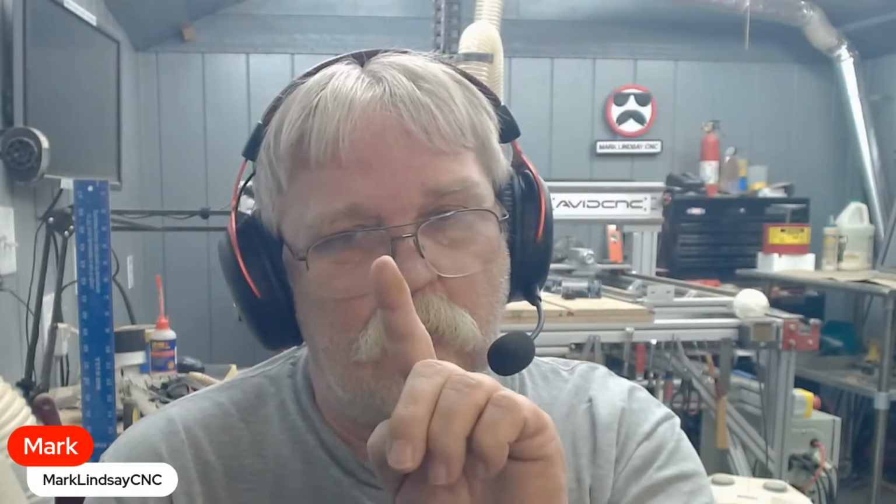To be honest, if you're cutting any of those materials, a single flute, O flute bit, and the O stands for open. It's an open flute bit. You've got the cutting flute, the cutting edge, and then it looks like a real wide, deep trench with a real steep helix, the real steep spiral.